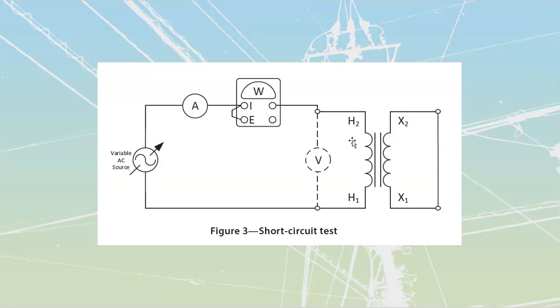Over time, transformers go through a process called degassing, where the VOCs, the volatile organic compounds, start to evaporate out of the varnish that's applied as my insulation. As that happens, the resistance of that insulation is going to change. I start to have more leakage and things like that, and so I start to get a change in my transformer's output. So we periodically have to take some of these transformers out of service and test them. You're going to see differing values for your core losses and your copper losses as a transformer ages. It's just, stuff is wearing out, right?